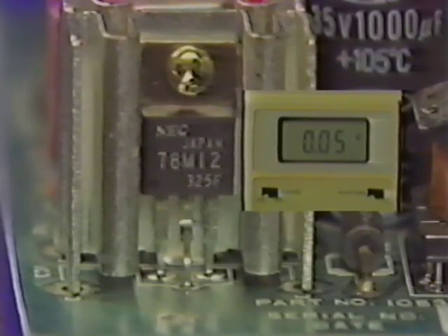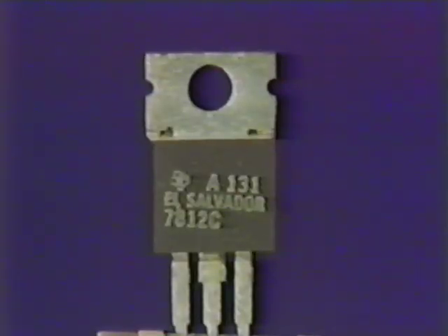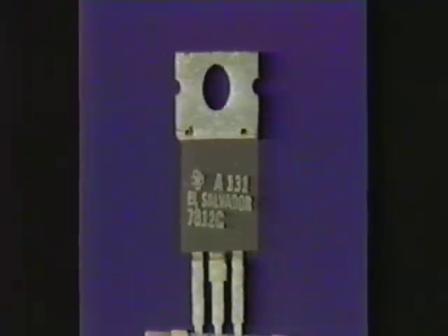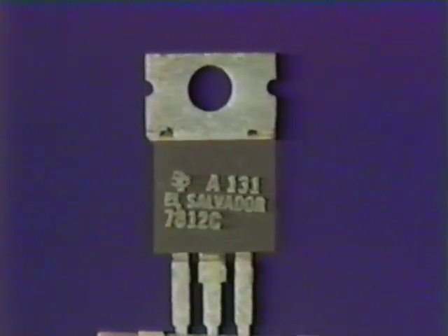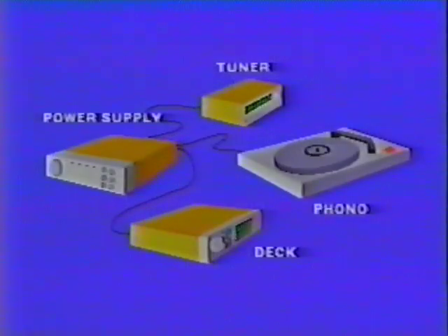Care should be taken when replacing 3-terminal regulators. Although they are quite hardy when installed properly, they will often be destroyed if installed backwards. Low voltage symptoms can also be produced by a failure in the signal processing circuit being powered. Observing the suspect load circuit for symptoms that point to the problem can often identify the trouble.